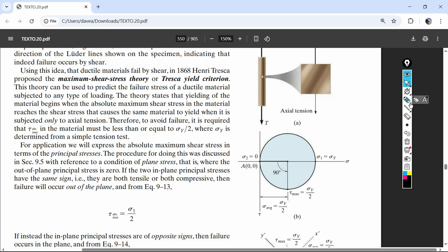On this graph, if you're in the linear zone, and it looks like this for steel, and this is your yielding. If you maintain this linear zone, you go up to here. What happens if you go up to here and then back off all the load? You come right back down to here. Every molecule goes back to the same location.